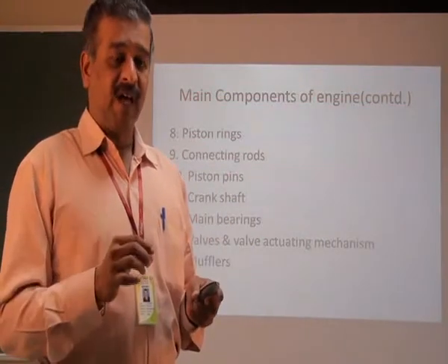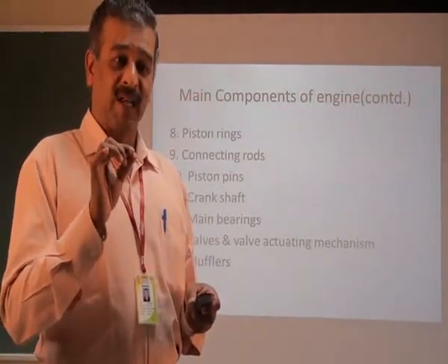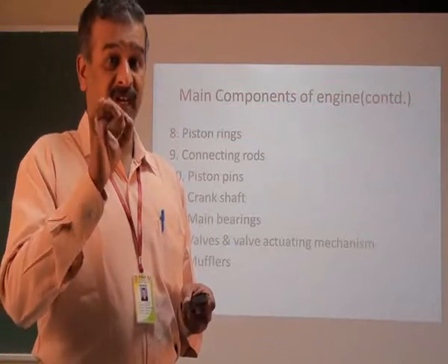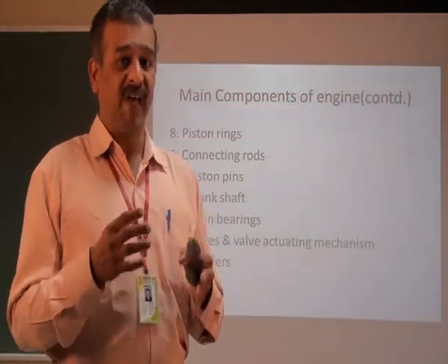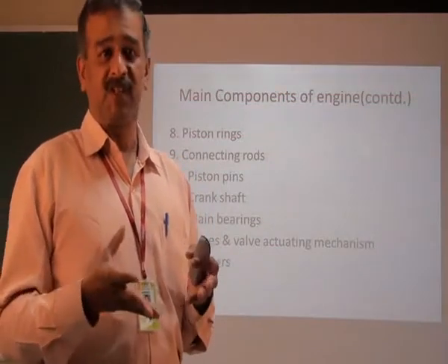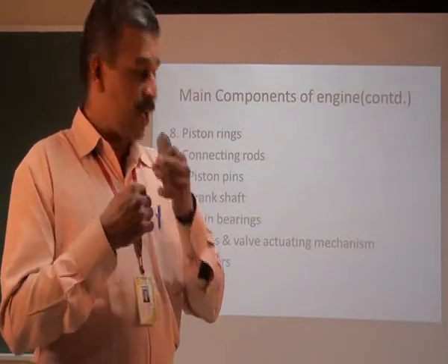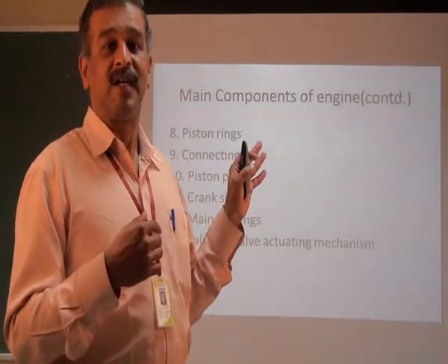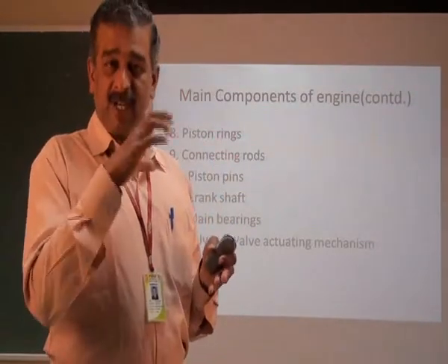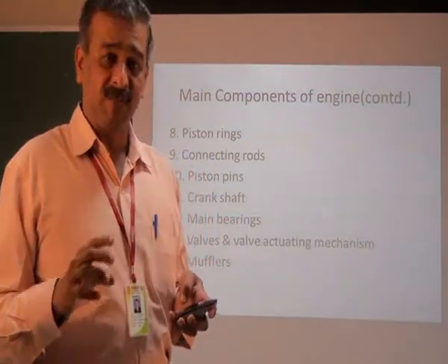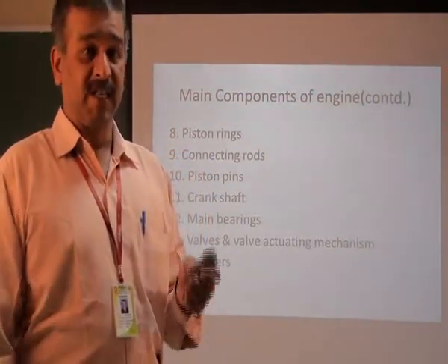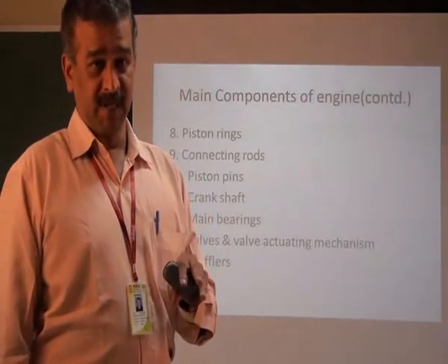So this valve has to open at the right time and close at the right time. If it is not closing, then what will happen? During the firing of the fuel, that is, the combustion of the fuel, the entire thing will come out through that inlet valve. So it has to be done in a proper way. That is called the valve and valve actuating mechanism. That has to be timed properly.